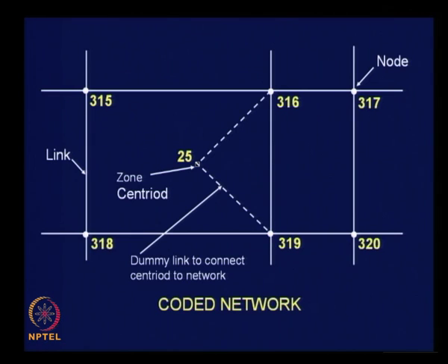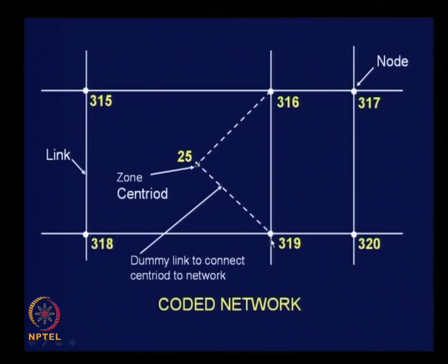And in this particular case, you can assume that entry into this network is not possible for these people, and they have to get connected to the main network only through these two intersections. Under such a condition, we are introducing only two dummy links. It represents the actual traffic flow in the field, and if connection to this node is prohibited, then we will have only one dummy link and everybody will be assumed to make use of only one path. Clear?